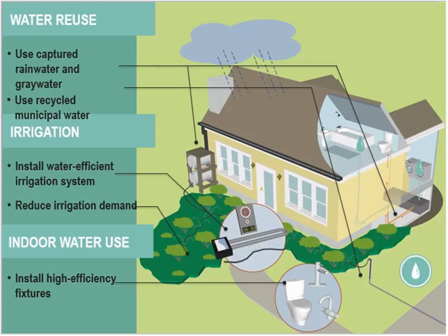Now, moving on to water conservation. This one's a pretty small section. It requires at least 3 points, and most people pick up their points in the fixtures section. On the toilets, you're looking at getting down to 1.2 or lower. We're seeing some really great toilets, single flush even at 0.8, and even lower than that, and they work great. They're very durable, so we know it can be done. You can get some extra points there depending on the flow rates of the toilet. I think it's 1.28 or 1.1 for the lowest or most points.